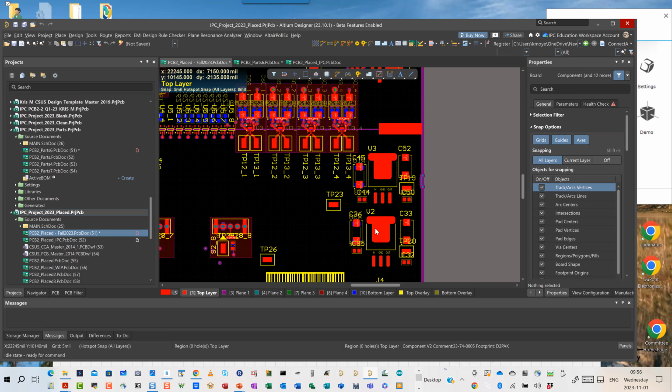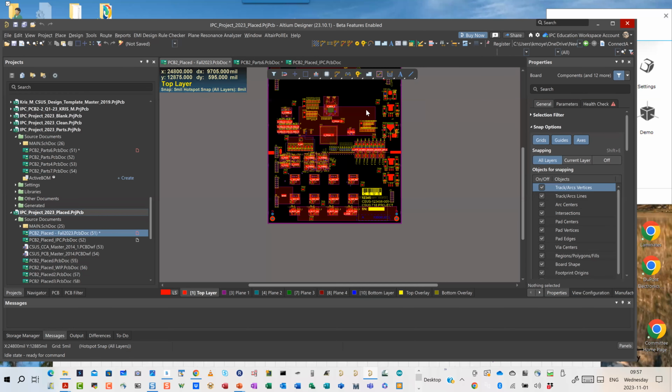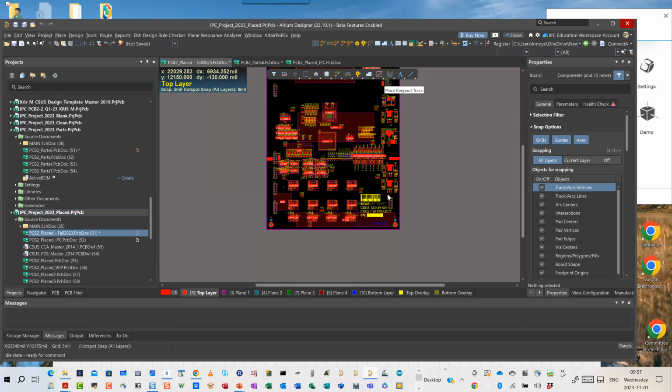I also moved my power supplies. It made no sense for me to put the plus and minus 15-volt regulators up in this area with all the digital circuitry, since they're going to have a common input of 28 volt and chassis. So I brought my 28 volt connector in here. I can just route 28 volt as a pour down into this area along with chassis down in this area. We'll see how I did that later. And then I can have my plus and minus 15 directly generating right in this area rather than having again to cross the boundary. So more on all that next week.